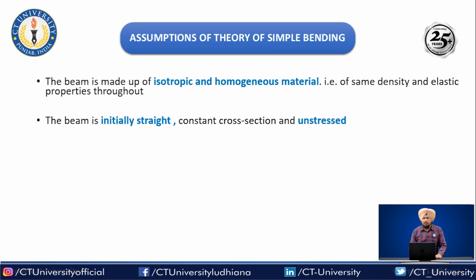Due to manufacturing there might be some changes in the cross section, say 2%, 5%, as it's not possible to make a perfectly consistent cross section, but for analysis we assume the beam has a constant cross sectional area consistent throughout the length, and that initially it is unstressed, so there is no initial stress in the material of the beam.